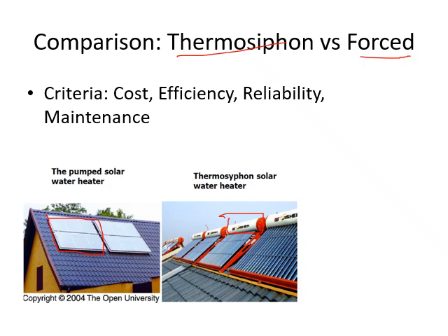So when you just see this plate, you can understand this one is the forced circulation, and the pump and everything is placed somewhere else, not here. It is here only to receive the heat from the sun and work as the heating fluid. While thermosiphon, the whole thing comes as one assembly, the tank associated with the water heating tubes.